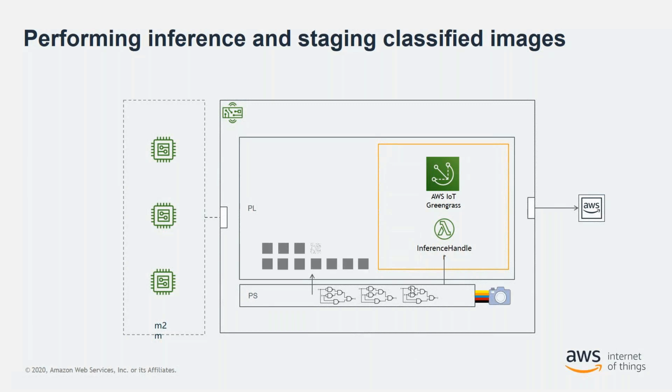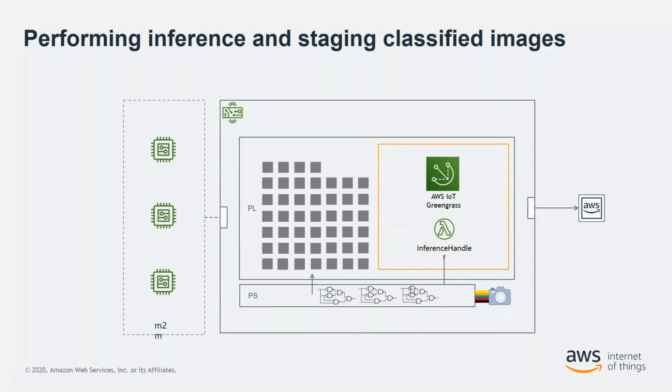And once you start doing the inference work, then you'll start getting results. Now, say, for example, we're trying to take a look at an inference where we find a human being in that compressor house that we talked about earlier in the talk. And if we see a person, we want to start loading images onto the local machine, right? Because eventually what we want to do is alert someone that there's someone in that compressor house, right? So we're actually taking the video feed that's going into the FPGA, it's doing the inference work, and then shooting back out through shared memory the images that it's capturing with the person that the machine learning model detected. Now, that's all good and fine. We have a bunch of images on that local machine, but we still haven't notified anyone on those inferences.